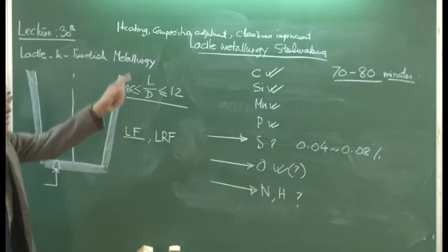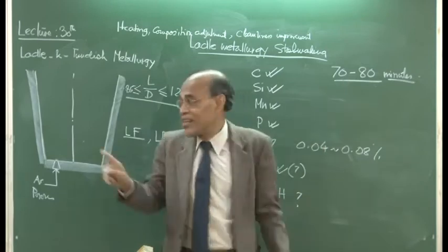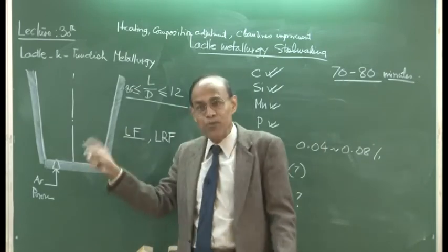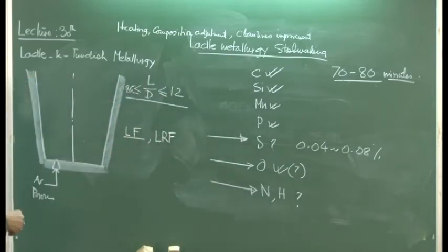Before we go and discuss these three things together, let us talk about the features of the ladle. So, let us come back. The ladles are equipped with a porous plug, and through the porous plug argon is going to be blown, because we know that for the next 70-80 minutes the material is going to be sitting in the ladle and the processing will go on for improvement of temperature, for improvement of quality and so on. The rate of heat and mass transfers are strongly dependent on stirring in the system, and we cannot use any reactive gas.